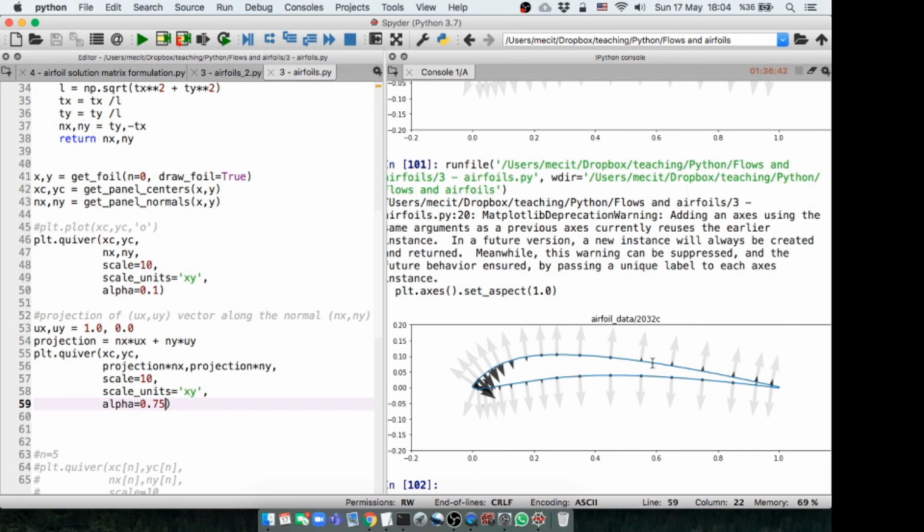But when the foil normals are more aligned towards the x-axis, we begin to see the projection vector. Something more I can say about this figure is basically these are the parts where the lift is created, or even better, the dynamic pressure is highest at these points, because at these points the free flow is really hitting the airfoil